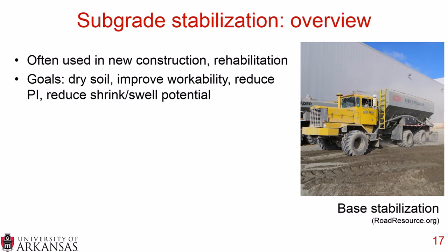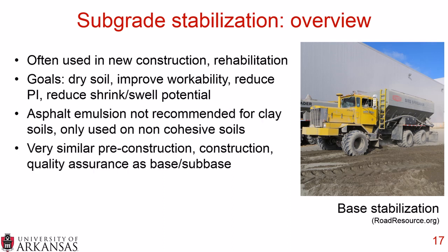The goal is to either dry the existing in-place soil to improve the workability, to reduce the plasticity index, or to reduce the shrink and swell potential. As we mentioned before, asphalt emulsion is not recommended for clay soils. It generally is only used for non-cohesive soils. And as I mentioned, there's very similar pre-construction, construction, quality assurance considerations as the base and the subbase.